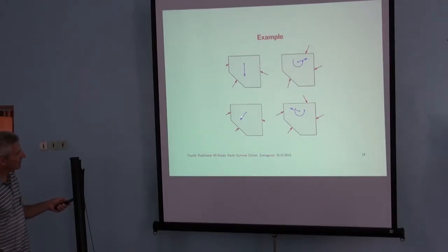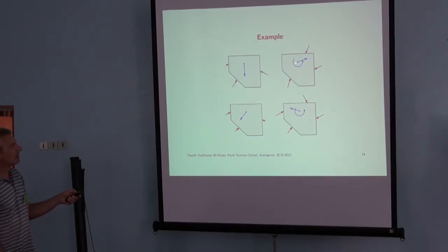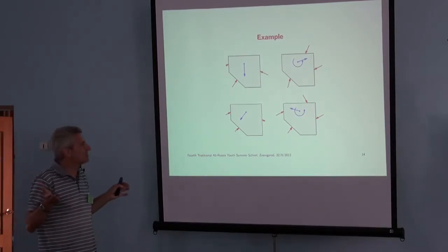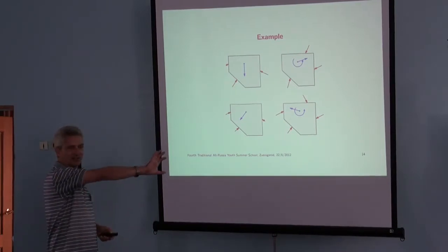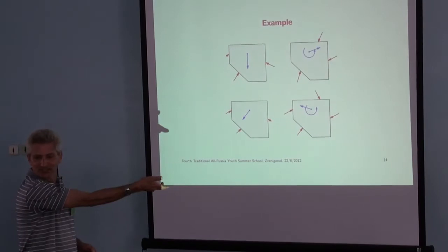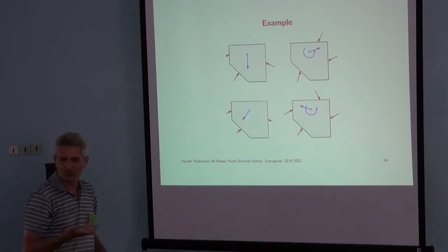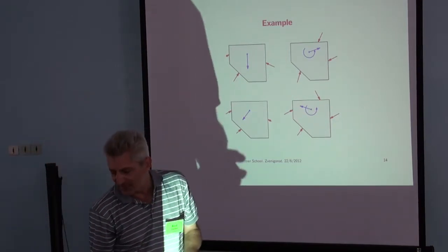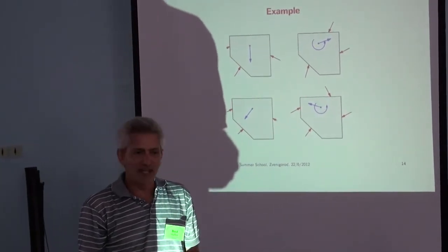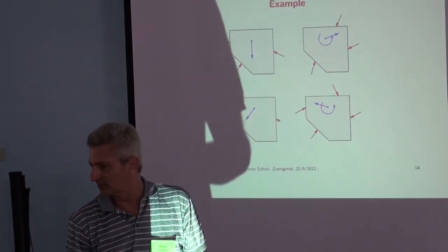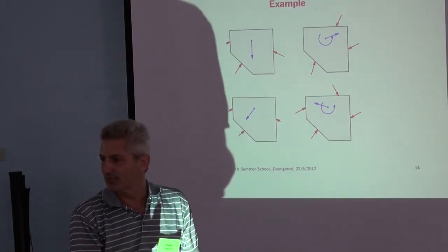Here's just a force in this direction, and you can sort of see what's happening. Now this one's on the friction boundary, this one is not, this one is. Here it's counteracting a force that goes this way and a torque that way, and you see the various things going on. Here's one where you have a strong torque this way, and so to counteract that, all of the forces are at the edge of their friction cone, not this one, and they're applying a counter torque. So nothing is counterintuitive about this, but at the same time, it would be a real pain for a human being to figure out what these are doing. And this is in 2D, and of course, you'd really do this in 3D, not 2D.